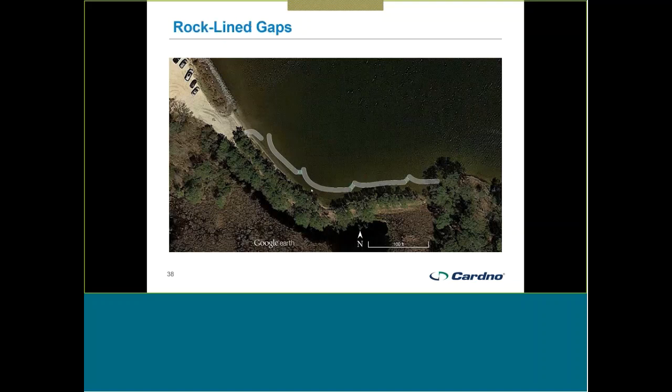And the distance offshore was established basically trying to balance. We wanted about 20 feet of low marsh and 20 feet of high marsh to get our average slope to be someplace around 20 to 1 in each of those zones. But it's a balancing act because you don't want to encroach too far offshore. I'll show some pictures in a second.